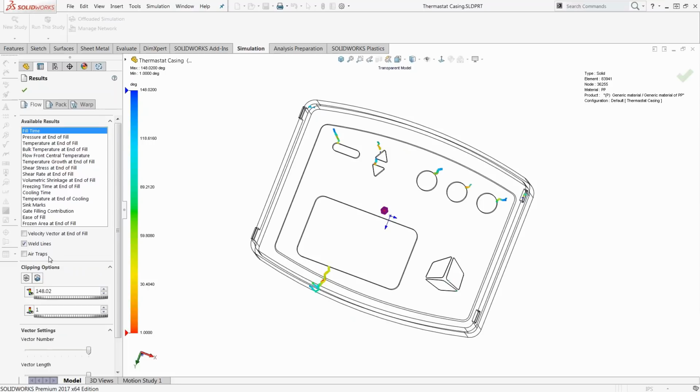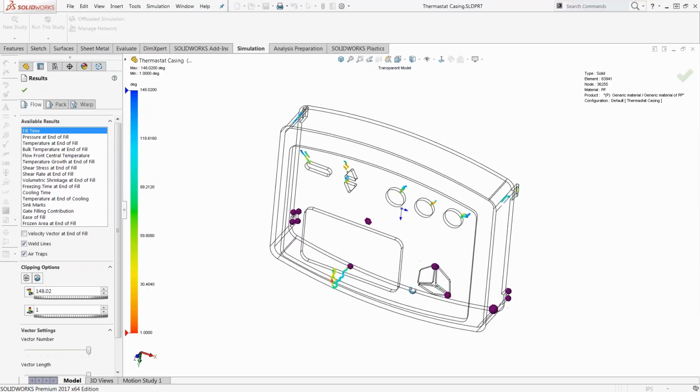Another thing unique to plastics injection molding is air traps. When we looked at the initial flow of how an injection mold machine is made, the gap between those molds before I inject any plastic has air in it. So where does that air go? That air needs to be vented out. And this is done through what's called venting lines.